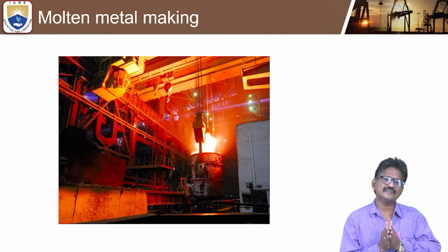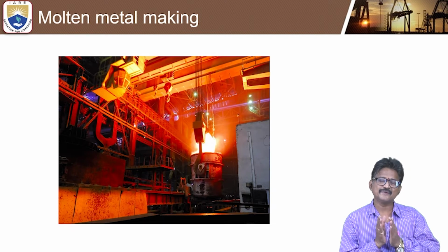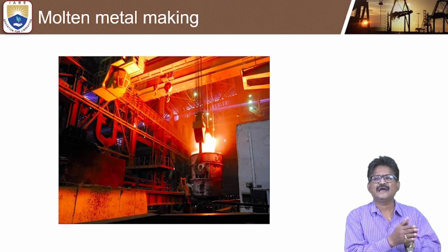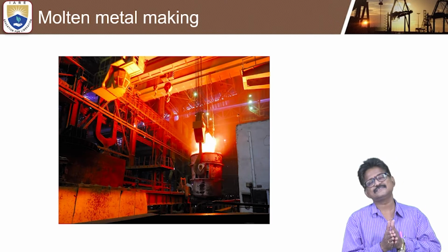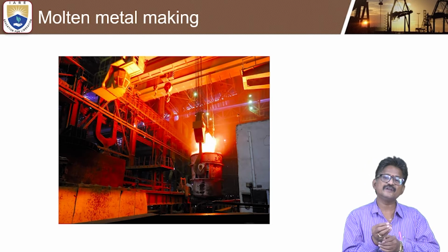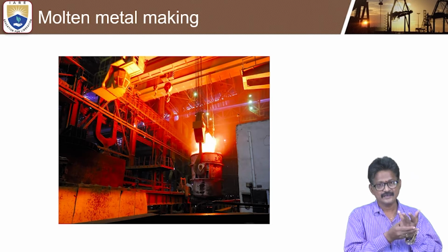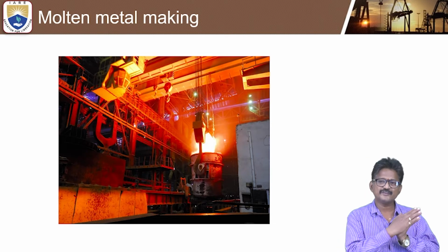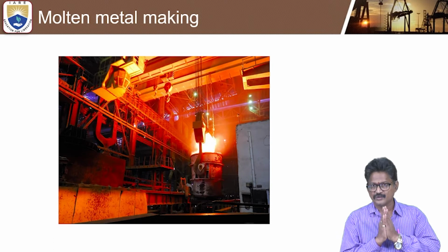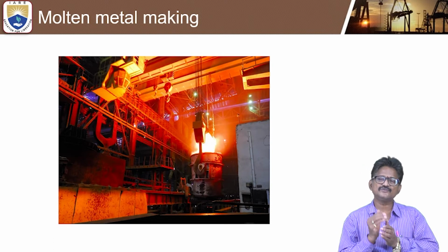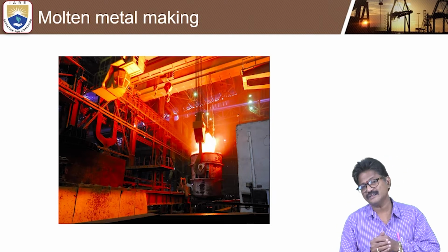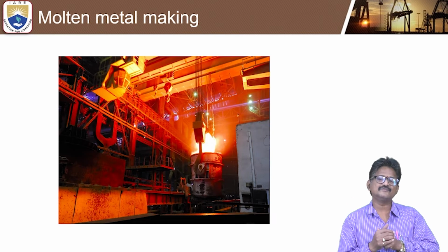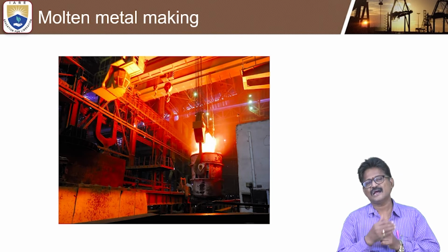While the molten metal is being prepared, the pattern and the sand mixing are prepared, and the mold is made with machine molding and hand molding processes. Once the series of molds is prepared, parallelly, about two hours before we start, we bring the molten metal and pour.